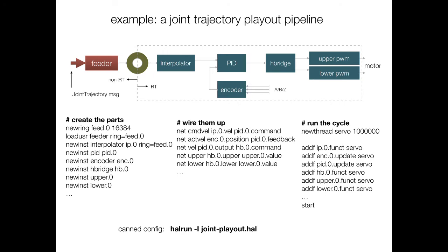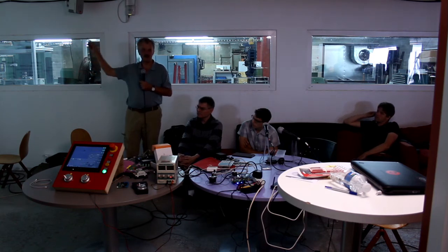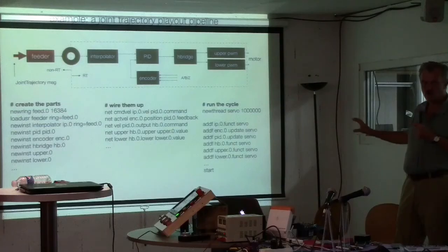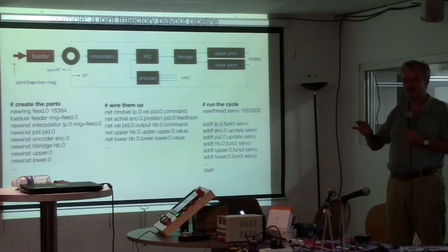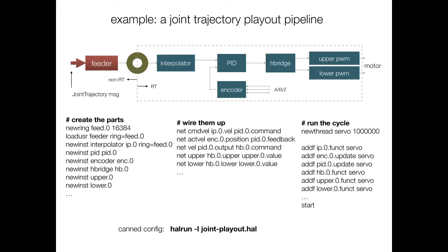And from there on, the whole configuration is alive. It starts listening to commands here, and does the interpolation, does the PID loop, does the position sampling, but it's all built out of reused components. We have not done any programming at that stage. We've just reused standard components. And that is what you do when you adapt Machinekit to a new machine.